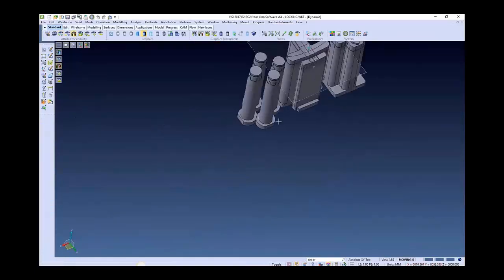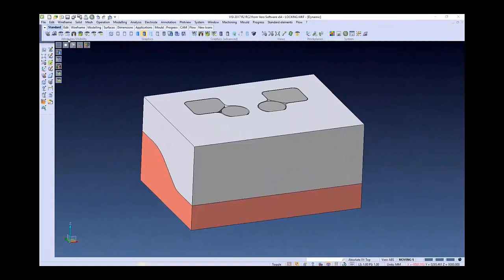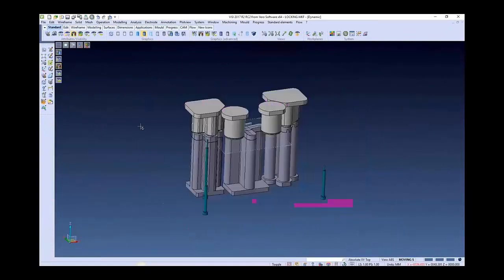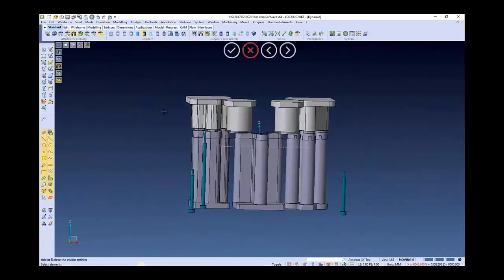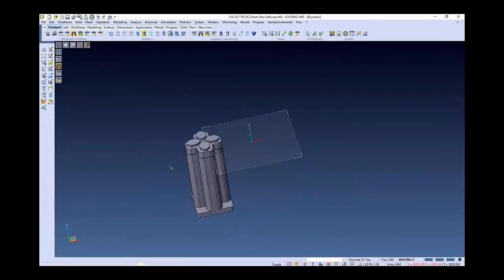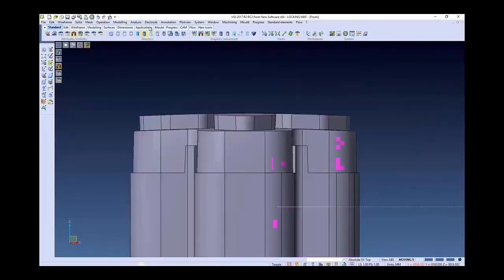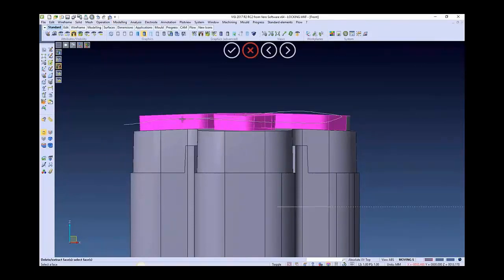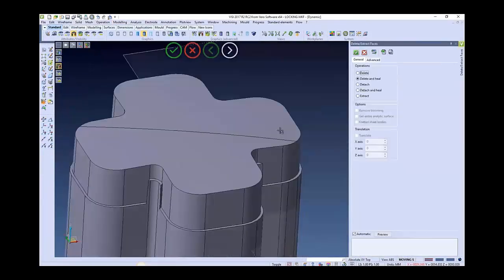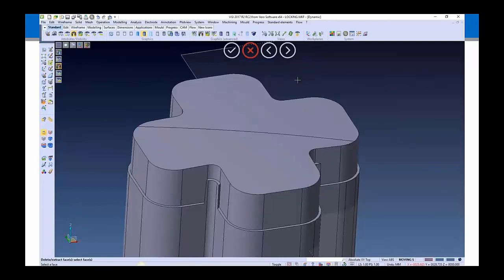So in here, using some of the different options here for visibility. And using that brush selection. So we're going to take out some things using that brush selection. It's just a different way, instead of windowing in, that you can use on the fly. So on here, normally where I might window in, you can just kind of draw over, drag over, and select those surfaces. Especially on a curve like that, that straight box doesn't work quite as well. So that brush selection, that'll work for you in that instance.